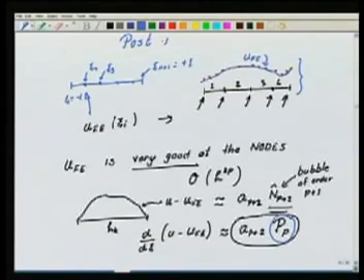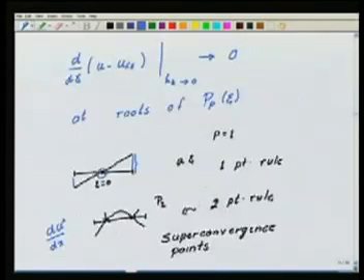So, what we are actually doing now, as with the previous transparency, is that we are in the regime of the post processor. Once the solution is obtained, we are talking of how best to interpret our data, to represent our data, and how best to extract something better from it. So, I would like here to get a better value of du star dx from my dufe dx. Okay. I know that I can use the values of the derivative of the finite element solution at these points, which correspond to the roots of the Legendre polynomial of order p, which are nothing but the p point integration rule.